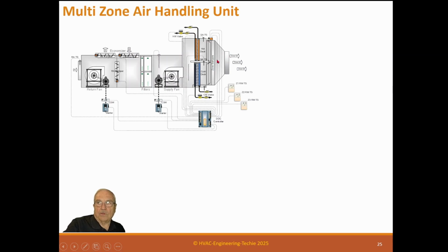The way this works is normally these dampers come out with damper plates every 6 inches, or maybe every 4 inches, and then they gang together as many as they need for a zone. And then they put an actuator and you link them together so you get the zones. And that's how you set the zones up in the field, because these are all different. When I was a designer back in the day, we used a lot of these, and I've had up to 11 zones. And you want to try to design the 11 ducts coming out of an air handler. It's very, very difficult. So I'm glad these are not around much anymore. They're still here, but they're not much.